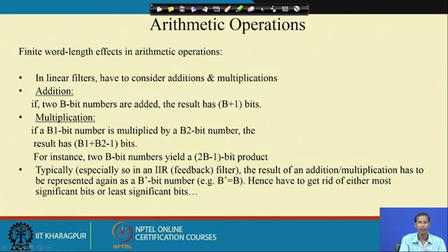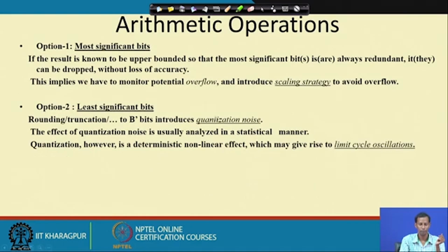Okay. Running in a loop means that particular point basically affects the overall performance of the filter. So, at that time I have to be more cautious while considering the word length for this multiplication as well as this addition operation. Okay. For the FIR filter it does not affect that much, but for IIR filter design, the truncation in the arithmetic operation, or the word length selection, affects a lot. Okay.